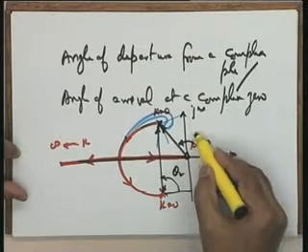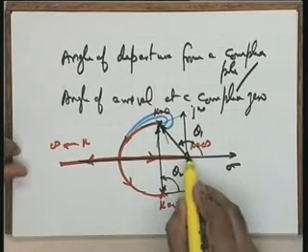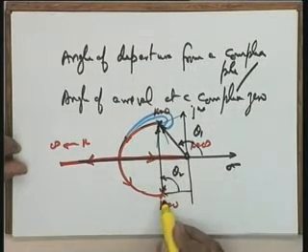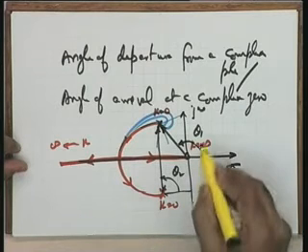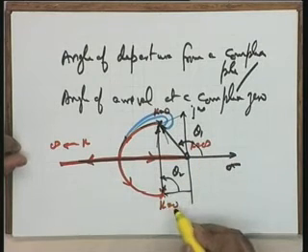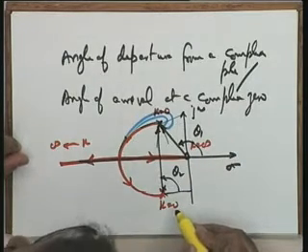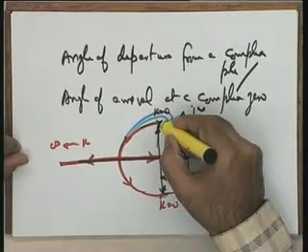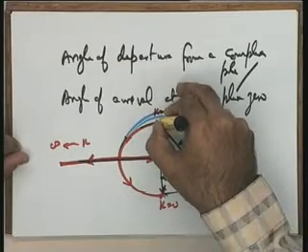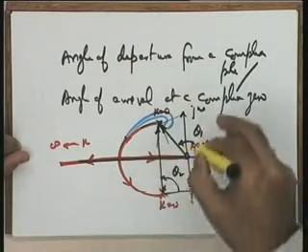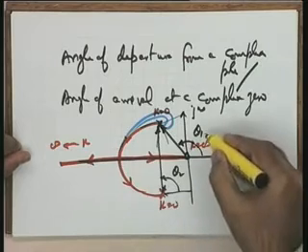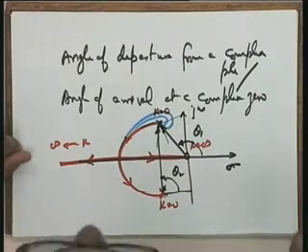It is theta 1 minus theta 2, because theta 1 is because of a zero and theta 2 is because of a pole. So theta 1 is positive and theta 2 will be negative, being in the denominator. So the net angle contribution at this particular pole, because of the other poles and zeros, is theta 1 minus theta 2.